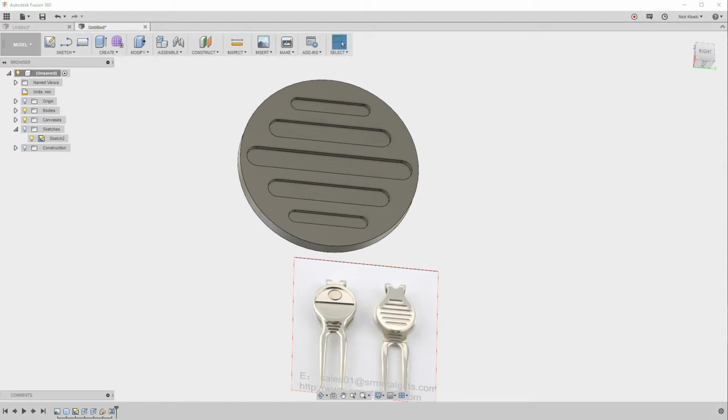The normal Prusa printers have just a single nozzle and are a direct drive extruder, which means that the drive gear that pushes the filament down through the heater is right next to the heater. It's all right there. When you upgrade to the multi-material, like this, I'm not sure if it's reversed for you, but I see it reversed on my screen.